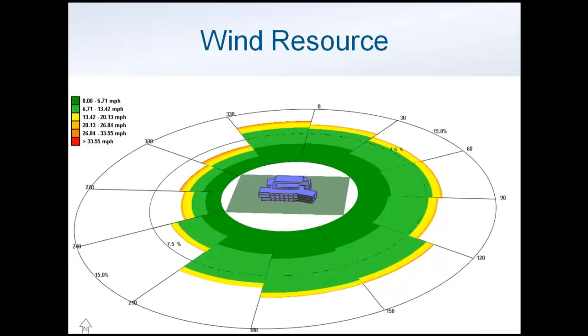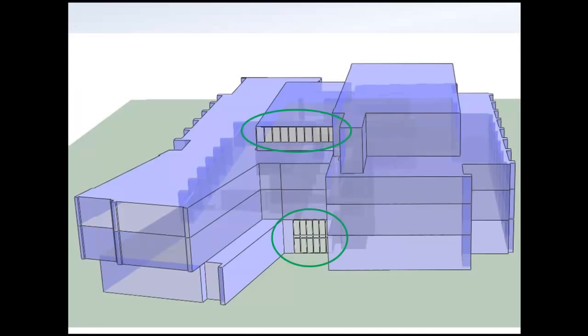And obviously, anyone who has looked in these data sets knows that the trick is to find wind data that is relevant for your site, and we worked awfully hard to do that. We ended up using the TMY3 data for Fort Collins, thinking that that was representative, especially since the project was going to be more of a buoyancy than wind-driven natural ventilation type project. So here is a picture as our building was imported from Revit, and I wanted to point out that this was a perfect import.